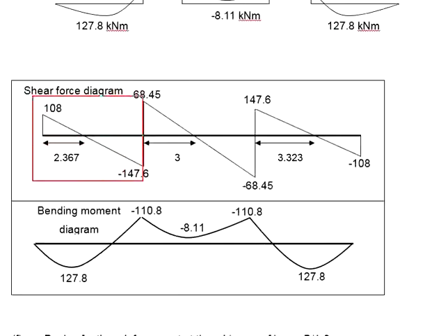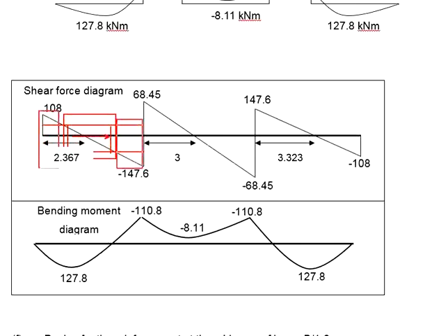Now, if you refer back to the shear force diagram here, you can draw two lines of 68.1 kilonewton. So whatever falls within the range of the 68.1 here, you can provide the minimum shear link. Beyond that, this part and this part will be the normal shear link. Now the question here is, how do you determine the location? You can do some simple interpolations to find when it reaches the point of 68.1 and when it reaches the point of 68.1, and this will be the range for the minimum shear link.